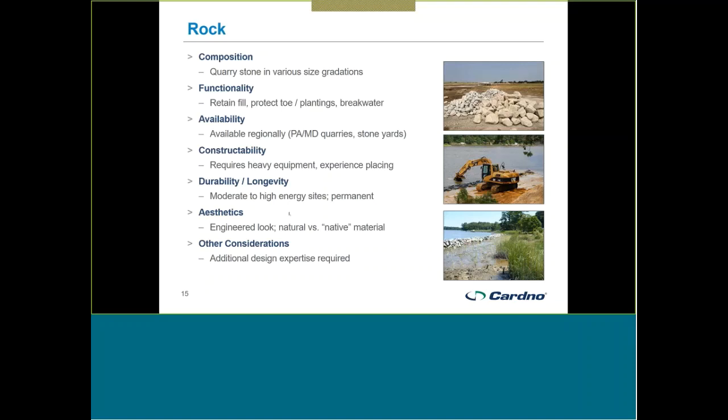There are some concerns, depending on who you talk to, about the aesthetics of using rock in living shorelines. It does have a more engineered look to it. It's definitely a structure. You look at it and say, yeah, that's a man-made structure, versus other design techniques with a biolog, where you may have a hard time distinguishing that it is a restored shoreline. And then from a design perspective, it starts to bring in the need for some civil and coastal engineering type expertise to make sure you're sizing it correctly.